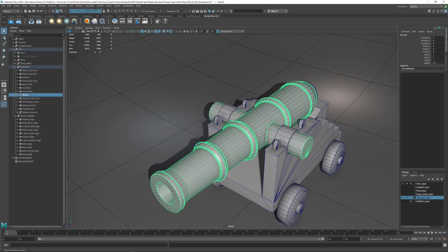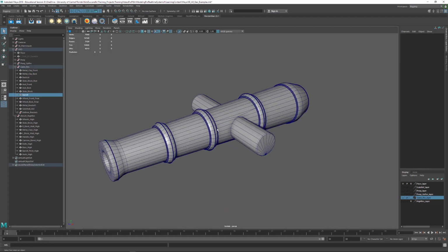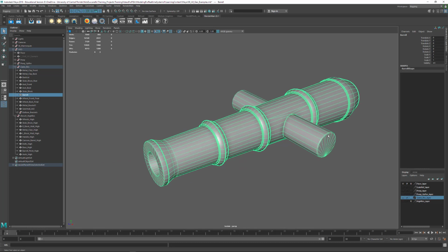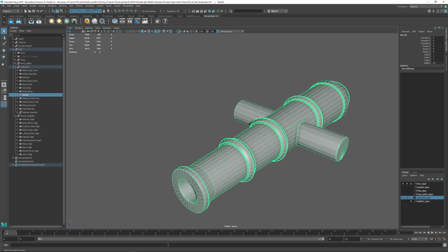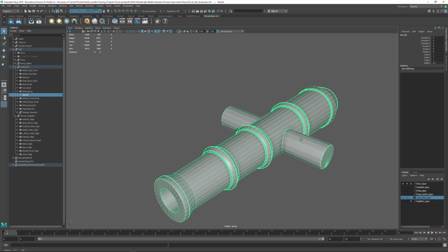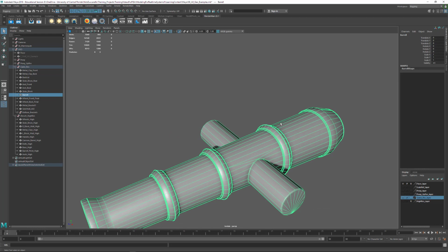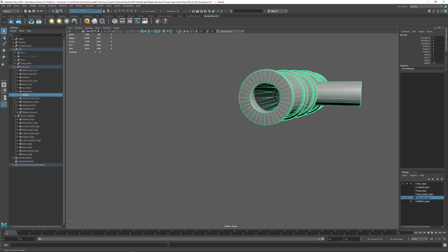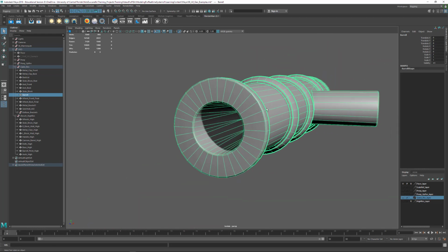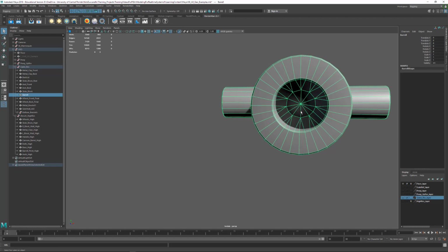If I select this and hit Control 1 and take a look at it, what I did was this piece within here, I rounded the ends, but then instead of just letting it go through and intersect with that shape, letting two shapes intersect, I actually booleaned them together, and then I added a bevel through here to get a nice little transition. The other thing is we mirrored things. We pulled some of these points down and made them end coming through here.